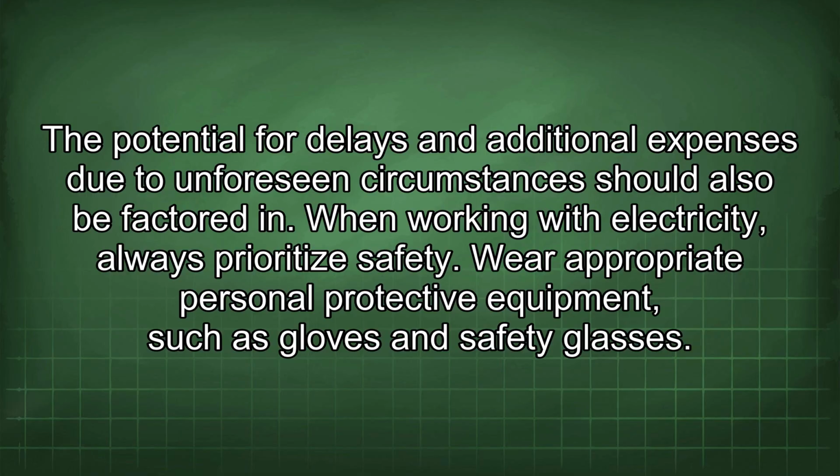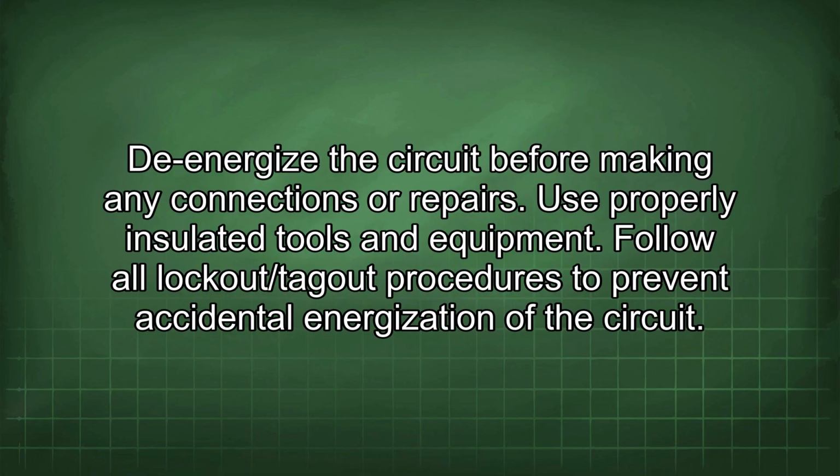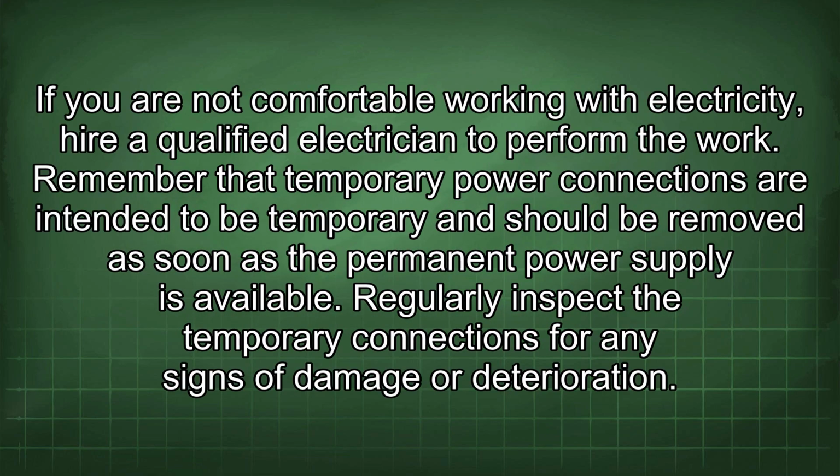When working with electricity, always prioritize safety. Wear appropriate personal protective equipment, such as gloves and safety glasses. De-energize the circuit before making any connections or repairs. Use properly insulated tools and equipment. Follow all lockout/tagout procedures to prevent accidental energization of the circuit. If you are not comfortable working with electricity, hire a qualified electrician to perform the work.